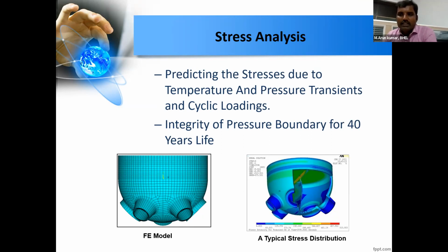We are doing n number of problems and comparing the results with the textbook results, or with the calculated results, or with the obtained experimental results, against the predicted results in the computer program. For those results we are giving an allowance of only 2%. If it matches within 2%, then only we proceed with the stress analysis.